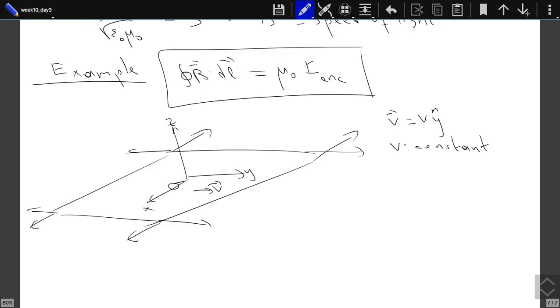There is a current. Okay, there is this wrong usage of terminology. The system is not static. It is more precisely described as steady. Nothing changes in time. Static means no motion, basically. There is motion here. The plane is moving. But nothing changes in time, so it's steady.